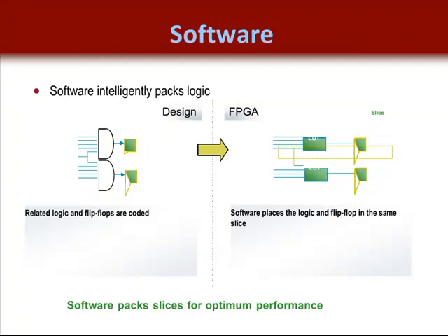For the sake of our discussion, it is important for you to remember that the implementation tools will try to group LUTs that have common inputs and flip-flops that have common control signals into the same slice. This will assure good performance and high device utilization. In the cases where designers infer lots of different control signals in their design, it's those cases that prevent the implementation tools from grouping them into the same slice.